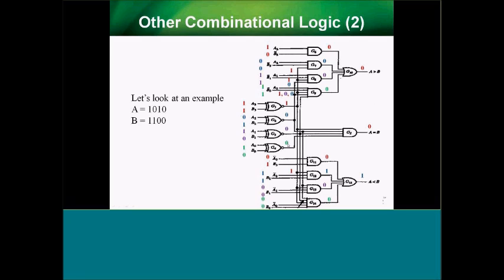But what ends up happening here is that these 4 signals, of course, are going to this AND gate, and that says 0. Since one of these is not the same, it says it's not the same. Then it goes up to here, and it takes each bit, flips it over, and starts comparing, putting it to an AND gate. It's quite a clever circuit because for the next bit, it has to include the most significant bit, and this one has to include the two most significant bits. So as it goes through this analysis, all of these AND gates become 0. Therefore, A is not greater than B.